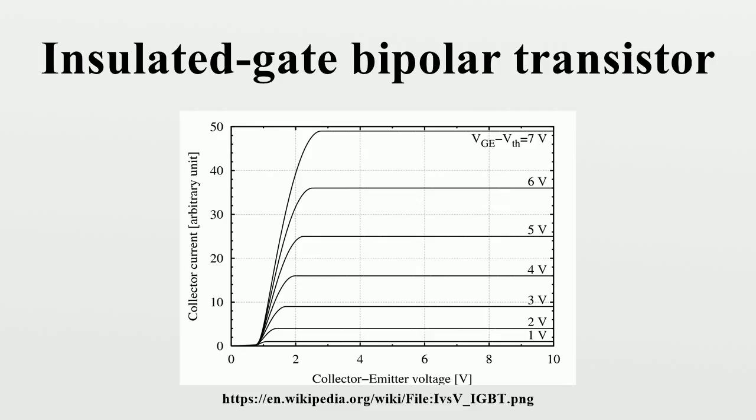IGBT models. Rather than using a device physics-based model, SPICE simulates IGBTs using macro models, a method that combines an ensemble of components like FETs and BJTs in a Darlington configuration. An alternative physics-based model is the Hefner model, introduced by Alan Hefner of the NIST. It is a fairly complex model that has shown very good results.